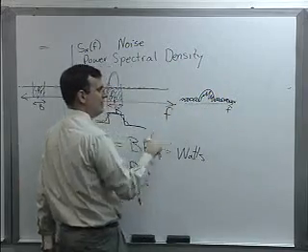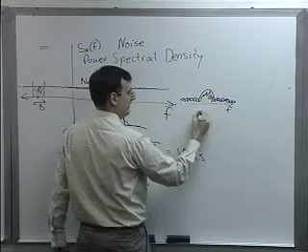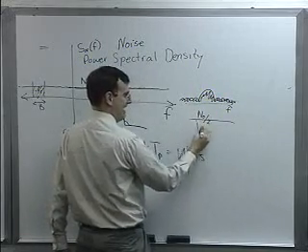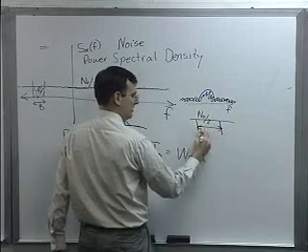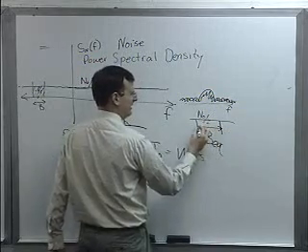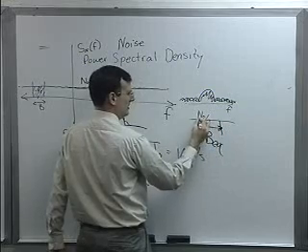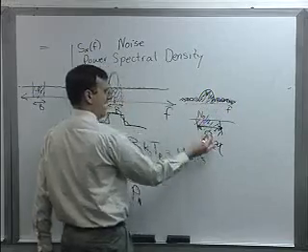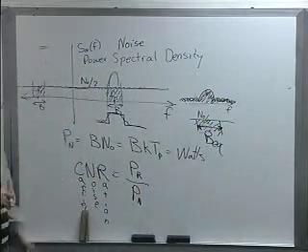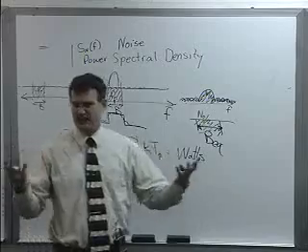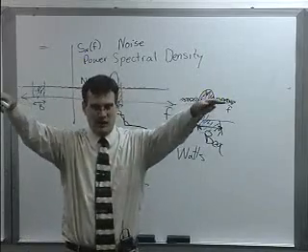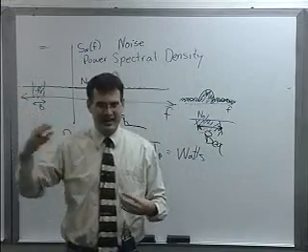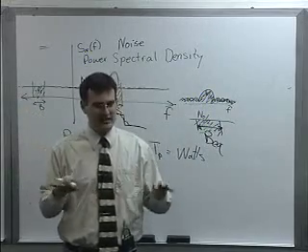And they basically say, well, if the noise level was flat at N0 over 2, and I had an equivalent bandwidth, B equivalent, what is the width of that bandwidth so that the area under this curve would be the exact same as the area under this curve? That's what they call the noise equivalent bandwidth. It's the bandwidth that allows me to approximate it as a flat noise power spectral density and pass it through the system with my kTB type equations that assume flatness.